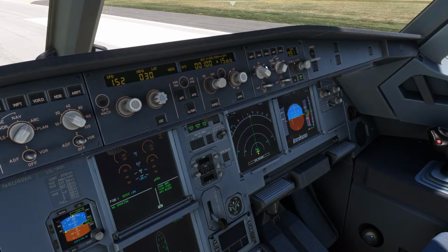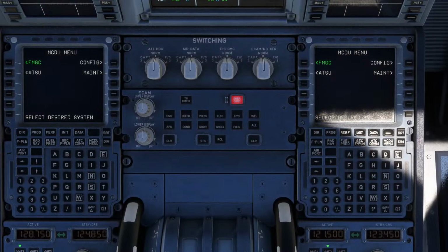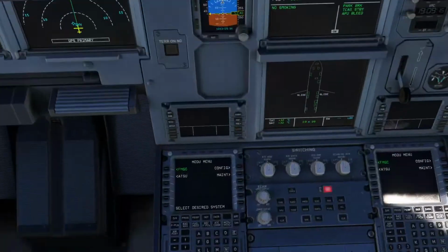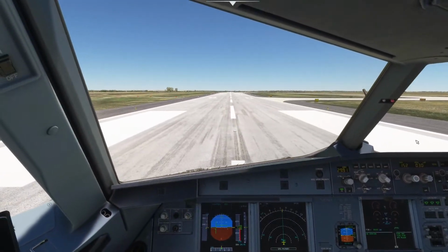If you're pushing the button in, think of it as giving the airplane the authority to do whatever is in the MCDU down here, which there are two of, captain and first officer, and it doesn't matter which side you program. I think if you're the pilot flying, you're programming. I'm not sure about that, but they both do the same thing, and it doesn't really matter at this point. We're just talking about basics.